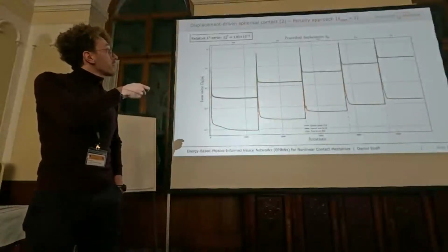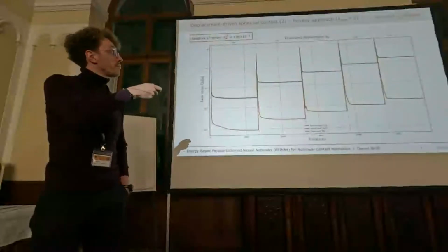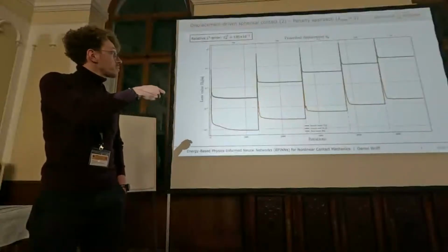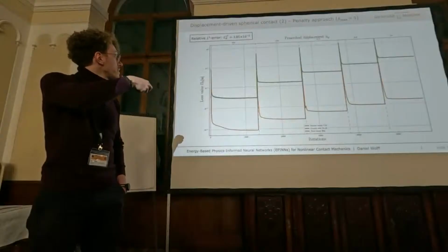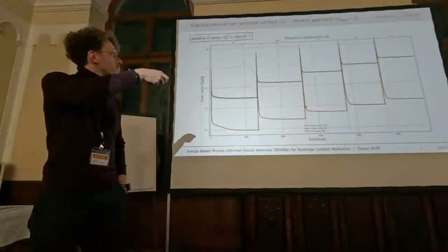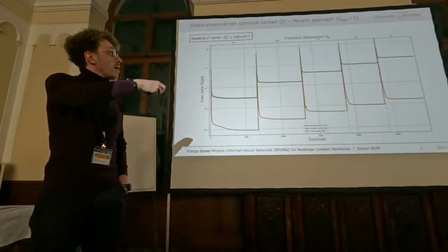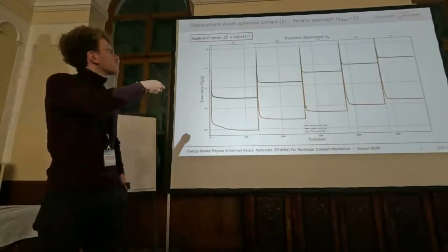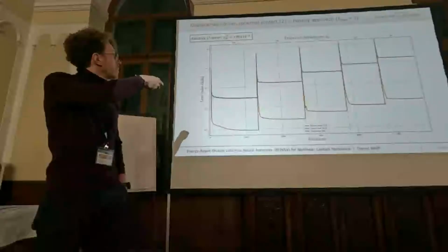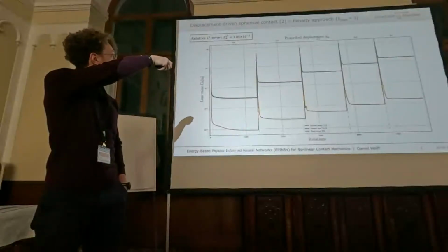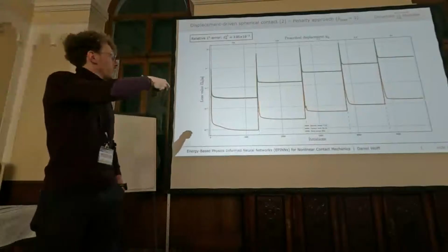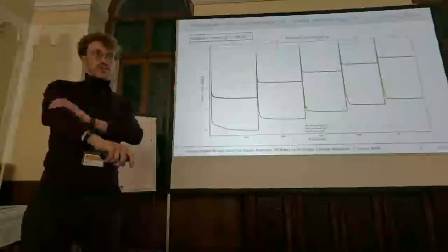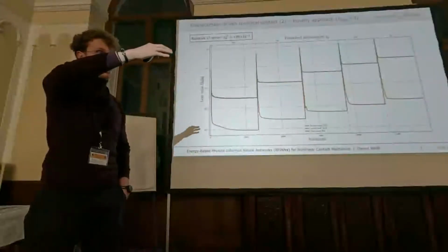So what we see here is, first, for the penalty approach, we use 5 load steps. So you can nicely see these 5 different plateaus here. You see 2 lines basically. The green line is mostly the total energy, right? And you see that it increases over the duration of our loading scenario. That makes sense because every time we have this jump here, it means that we increment our load. By incrementing our load, we introduce energy to the system. So this is why the overall energy increases here.